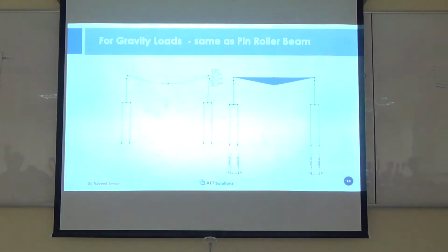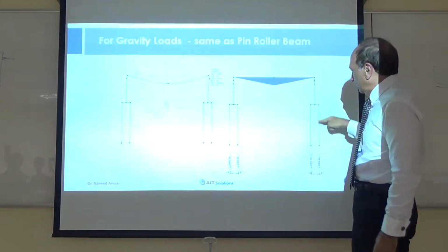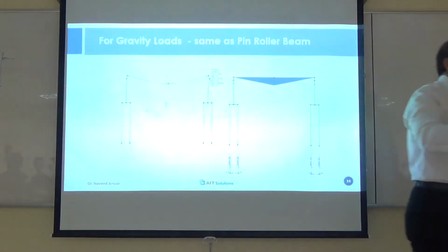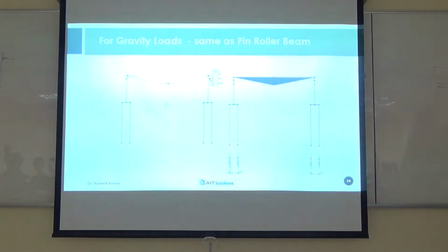Because the girder is not modeled at a center line. The girder is deforming, is rotating, that rotation is moving the bearings, that movement of the bearing is causing the column or pier to move and causing bending moment in the column and foundations. So there is bending moment there, but you also get reactions, so you get the whole thing in one go. You get pile forces, you get everything in one go.